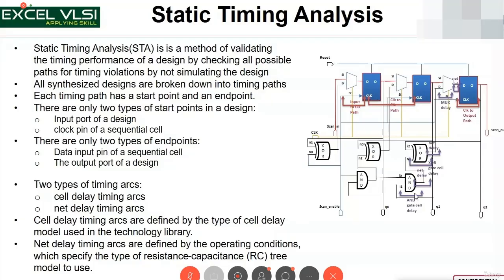So now more of it. STA is all about these calculations, taking the delays into consideration and checking a few more things like setup slack, hold slack, all this, right? So that's about it. Okay, so without simulating, how will you know the functionality of the system? Functionally, you would have done RTL simulation. That is where you have one level of confidence.